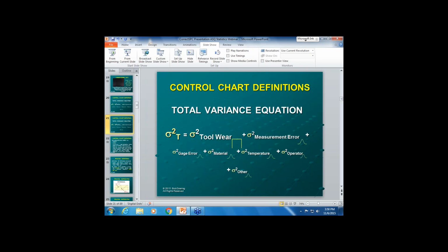So I've seen processes that you expect to have the sawtooth curve go up and adjust, go the wrong direction because of all the different effects on the tool pressure as everything's trying to get to steady state. That's just the way it is. So really, do you need SPC to determine that you have a special cause when you know you're actually within a special cause? Not really.